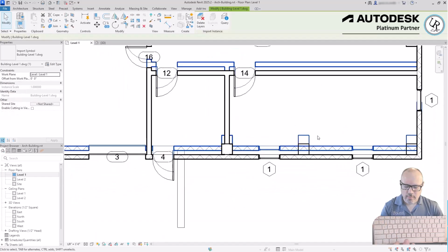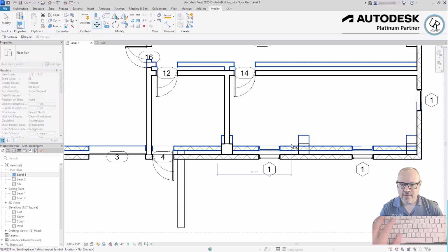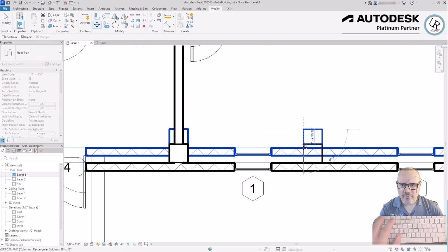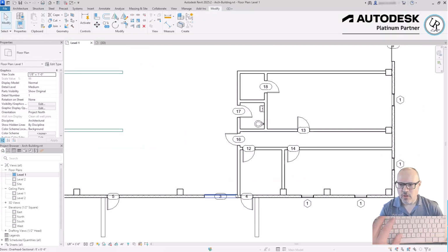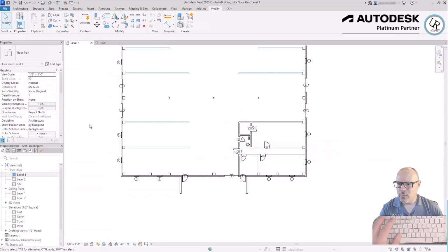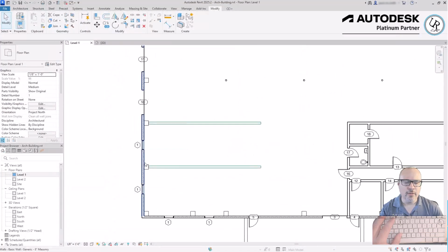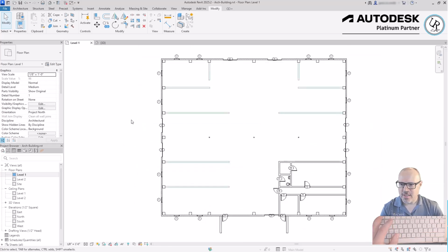You can simply use the move tool and physically move that from one location to another. As long as you have a static consistent point that you know where the object should move to, once you move that in place, it will stay in that location and not move. So even if the linked files are not brought in accurately as far as the coordinate position goes, you can relay them to other positions that are known or implied in the project.